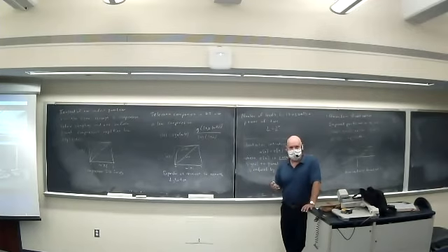Even long distance calls were transmitted using analog. These days, it's primarily just analog to the exchange, where it's sampled and converted to digital. Then it may be sent over fiber optics or coax or microwave, any number of different transmission media. But before that sampling takes place, they do this mu-law compression on the analog signal so that you get better sound at the lower volumes.